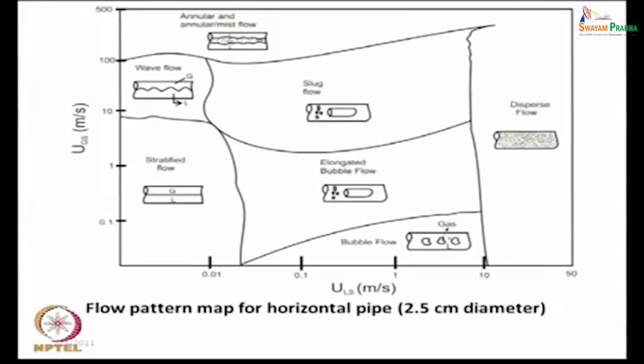For gas solid cases, we find that the Reynolds number and the Archimedes number, I believe you know about these numbers, are much more important. Usually, the maps for gas solid cases are in terms of CD versus Re, or maybe Archimedes number versus Re, and so on. I believe you have done a little of this in your undergraduate fluid flow classes, is it not? Some portion probably.